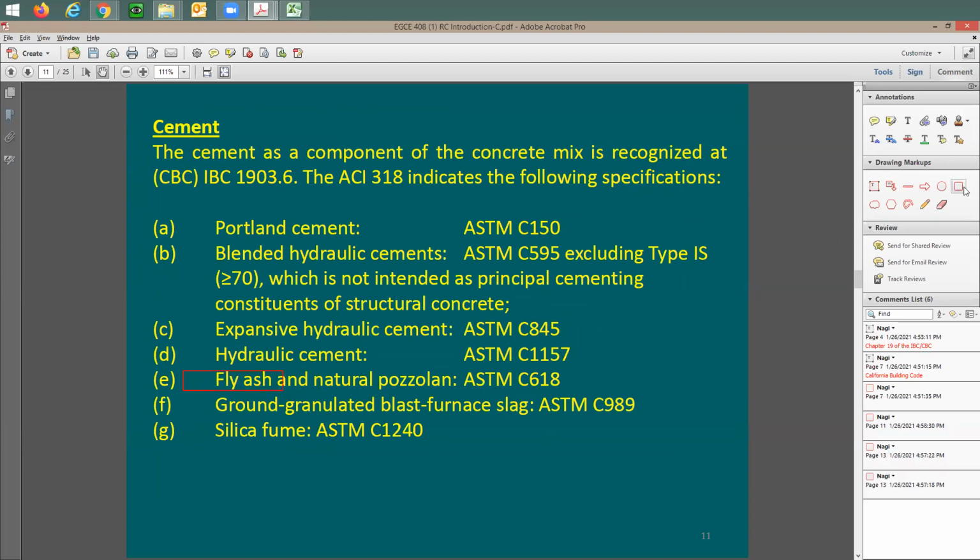And silica fume to substitute the cement. Instead of just adding lots of cement, you add fly ash and silica fume. With that, the shrinkage is going to be a little bit smaller, and it gives the same effect as cement. Also, this is cheaper. So it's a cheaper option to add a little bit of fly ash and silica fume, and this is called your cementitious material. You add it to the cement in your concrete mix design.